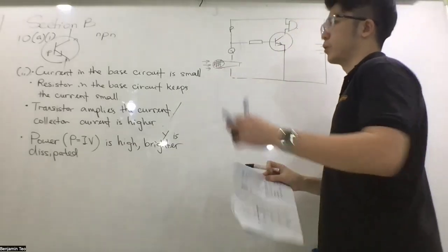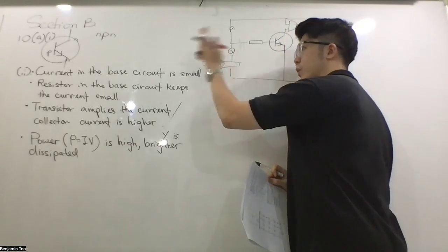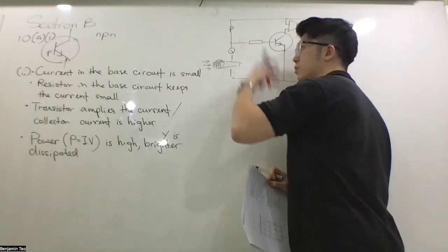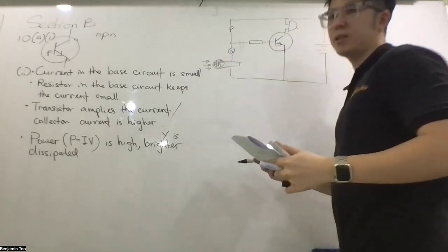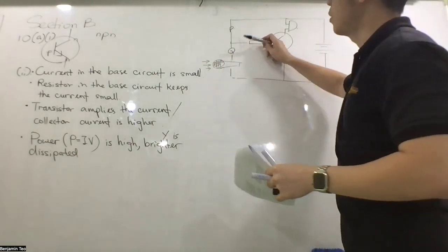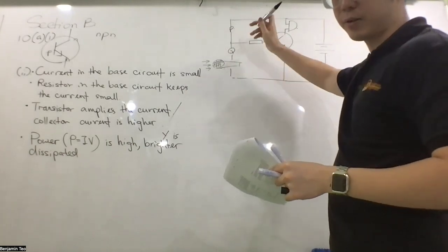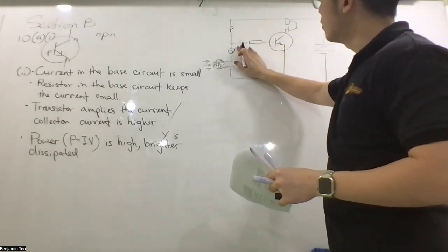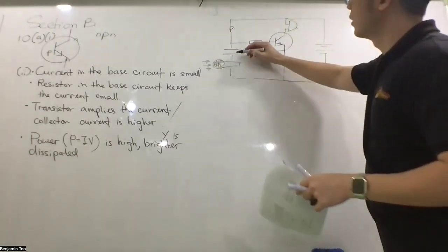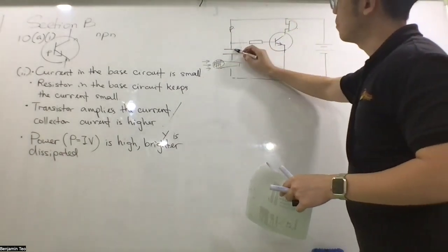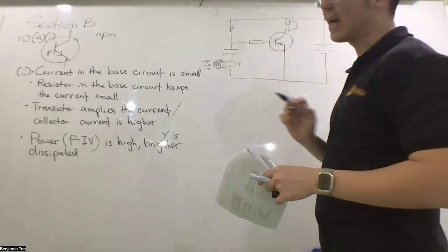So the microphone will produce voltage though. When it picks up the sound, it produces voltage. So current is generated from the microphone. It cannot receive current. Microphone is not supposed to receive current because it produces current. So the cue, you must put something that blocks the current, which is the capacitor. This capacitor is made of two plates with a gap in the middle, which is an air gap.